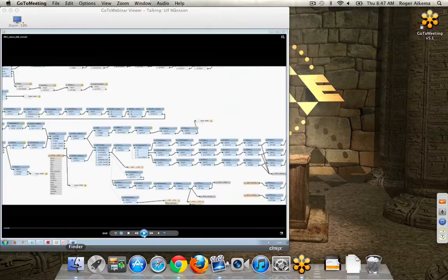Oh, that's a good question. We're actually working with the accuracy now, and what we are using are benchmarks that already exist in the power plant. There are small copper plates all over the plant that were put in there while they constructed it, where we have the actual points. So we're using those to control the accuracy of the model.